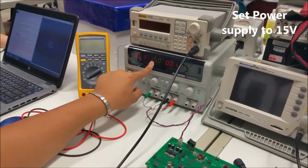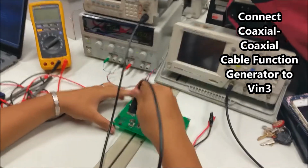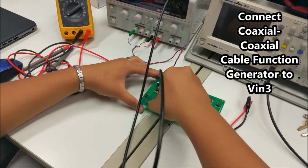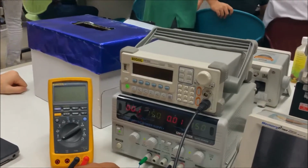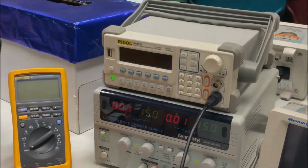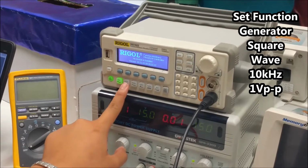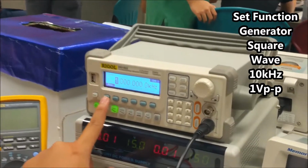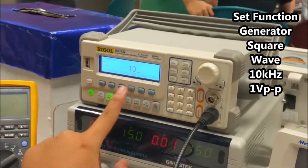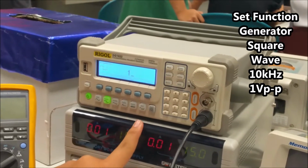Set the power supply to 15 volts and connect the coaxial cable from the function generator to VIN3 on the circuit board. Now turn on the function generator. This time, we will be using square wave for our measurement. Now set the frequency to 10 kHz and voltage to 1 volt peak to peak.